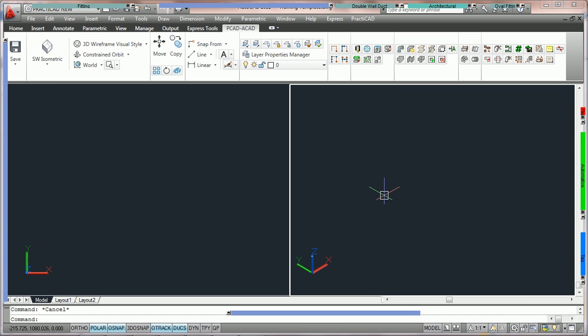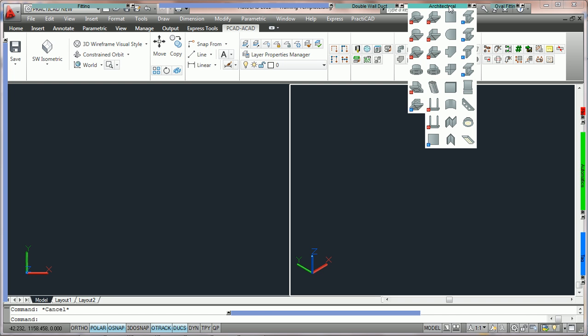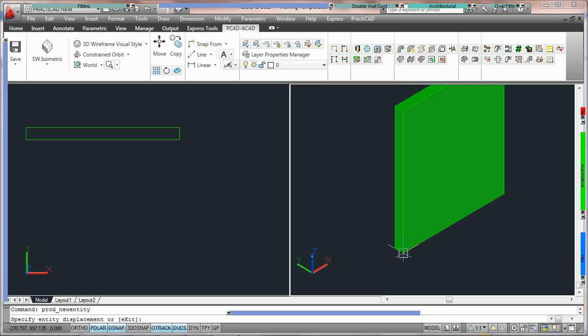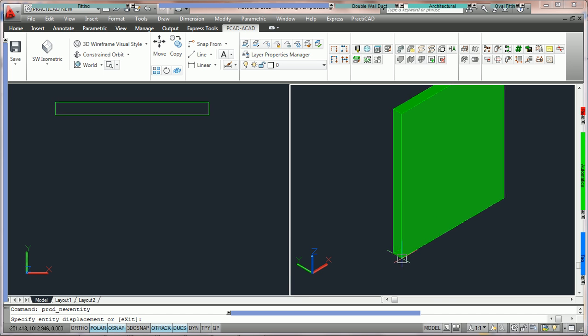The first wall type is the line wall. To utilize the line wall, we're going to go into the architectural bin, and we're going to choose the line wall icon. Here you're going to see that we are currently holding this by the bottom right corner, and this hold point is going to be adjusted in our item box.